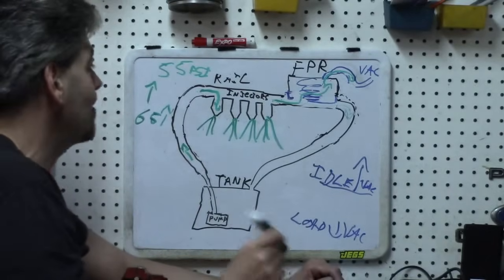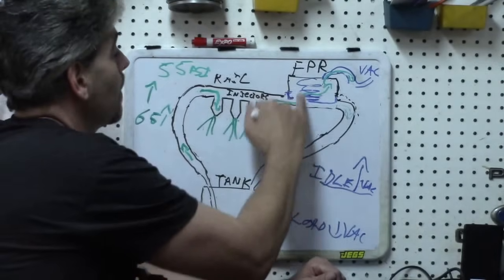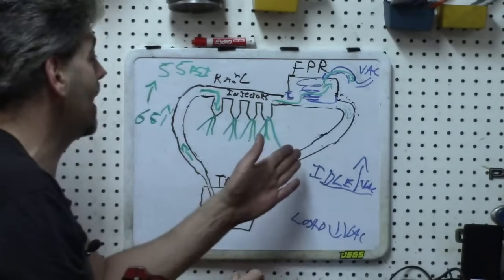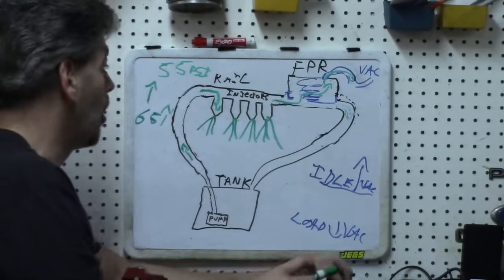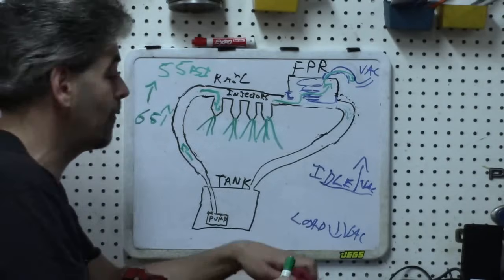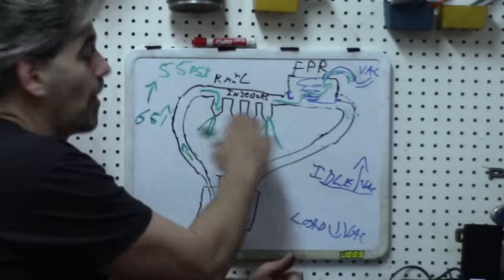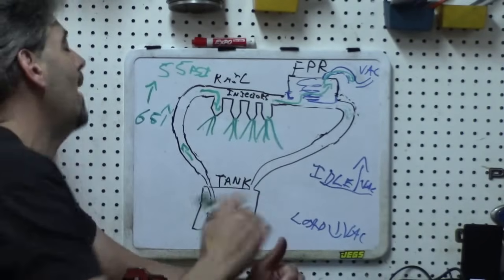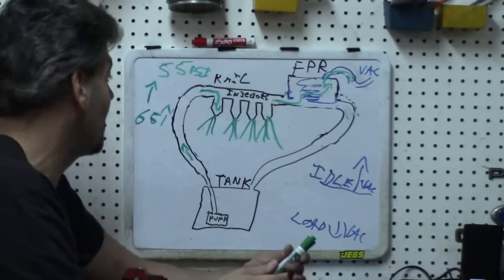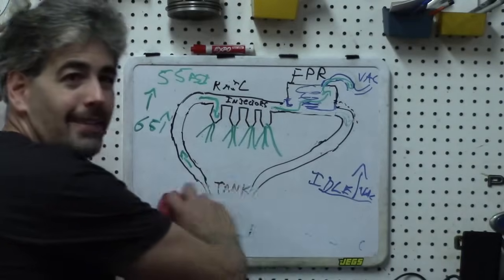The only reason that that would happen is you have a compromised diaphragm in your regulator and you will need to replace it. Almost certainly you don't need to do any further diagnosis. The fuel pressure regulator is compromised. You may have other problems too, but you also have a bad fuel pressure regulator in that event. All right, that is it.